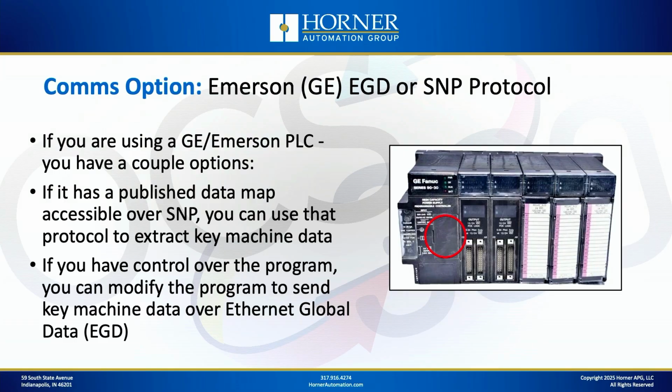However, there were a lot of machines developed using these particular controllers, and if you happen to have one in your stable of machines and you'd like to digitize that machine, the Horner controller is uniquely qualified to act as an edge device for this particular PLC, because we support all the native protocols of the GE PLC ecosystem, including Series 90 protocol, usually called SNP, and Ethernet Global Data, which is more than just a GE protocol, but it was a native protocol in the GE world. So again, if you have an old GE machine and you're looking to digitize it, the Horner is